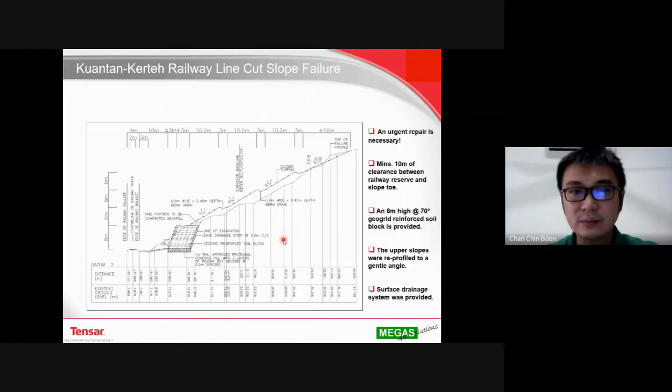So in our repair scheme, since this is a cut slope, by carrying out the tests to determine the soft layer and so on, what we propose is to build a stable steep slope at the bottom, and then reprofile the slope on top of it, including some backfilling, a gentle slope of 1 to 1.7, some gentle cut of slope on top of it, and provide very good surface drainage to drain away the water.